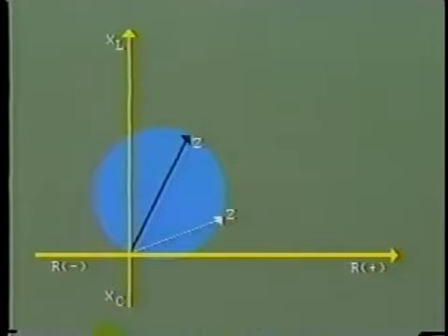This means that it is less susceptible to incorrect operation due to the load impedance, which can cause the relay's impedance to have a very low phase angle down here. Remember, this unit will only operate for faults within the circle.